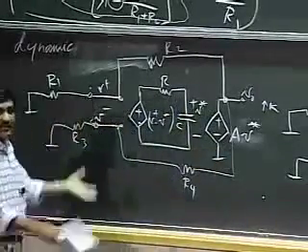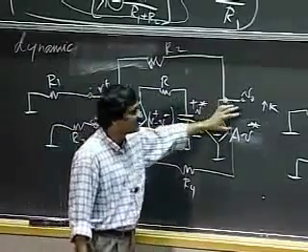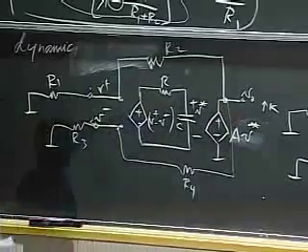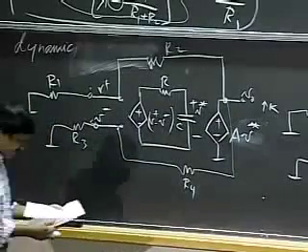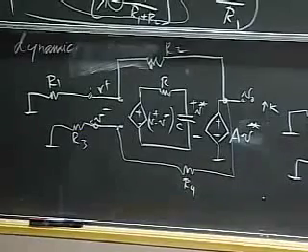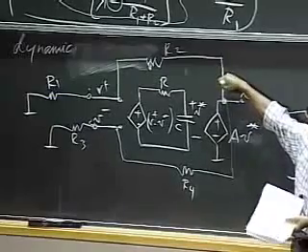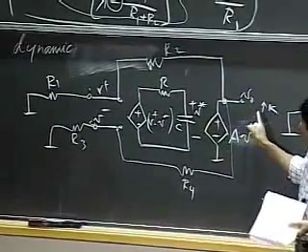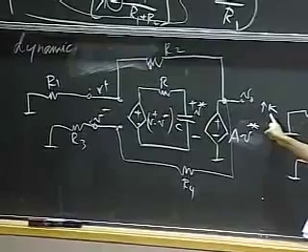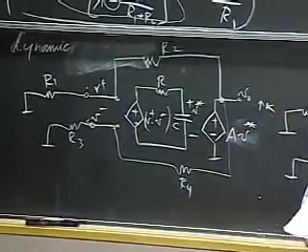And what we're going to see is what happens to the op-amp when the initial condition on the capacitor is such that this output gets perturbed to the value K. So let's write an equation for this little circuit and see what happens. Recall our goal was to understand what happens when I perturb the output a little bit. Here I perturb the output such that its value goes to K, and I can perturb the output by changing what happens at the capacitor.